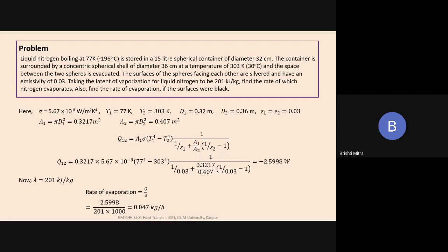So if you have ever seen a broken one of these vacuum flasks, and the reason they are called a vacuum flask is, you will see that the outside of the vacuum flask is silvered. There's a silver layer which is out here, and the reason they are silvered is, we will see right now why it is silvered, because we have less emissivity out here. So we try to reduce the emissivity of that particular material, so we silver the surfaces.